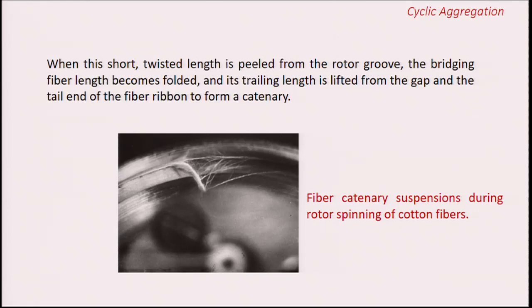Okay. Now, we can see this from this high speed photography also. As the yarn here, the peel off point is here, it is taken towards the navel here, right. So, the gap should have been somewhere here, but since it is only a few millimeters and fibers are continuously deposited, if the twisting torque is not high enough, then you may not even see the gap, it is so small.